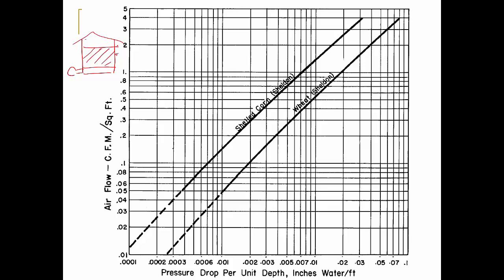The one key thing you want to understand is that in the mid-1900s, or 1950s, when Nebraska and other universities developed it, they flipped the graph axis. They put Q on the y-axis, which is the CFM, cubic feet per minute, per cross-sectional area, which is basically the velocity, right? Feet per minute. And on the x-axis, they put the pressure drop per unit depth of the grain.